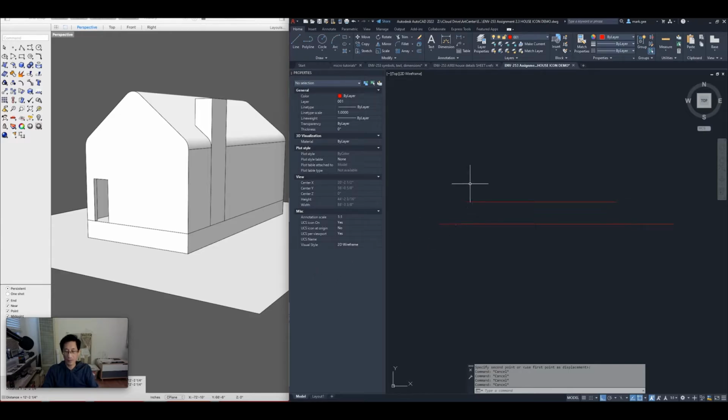So what I will do then is draw a line, start here, and go, oops, and I missed. Let's try that again. Line, snap, go up 12 feet, dash 2.25. Do it that way. It's easier to enter in decimals, okay?